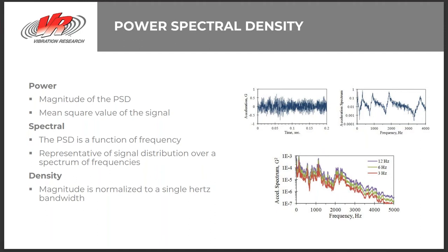The PSD plot can be created by an infinite number of waveforms, but when a PSD is defined, the GRMS will not change. This allows engineers to match a PSD to a specification and determine if the GRMS is as required. They can also use the GRMS to compare two PSD plots and verify that they are measuring the same amount of energy.